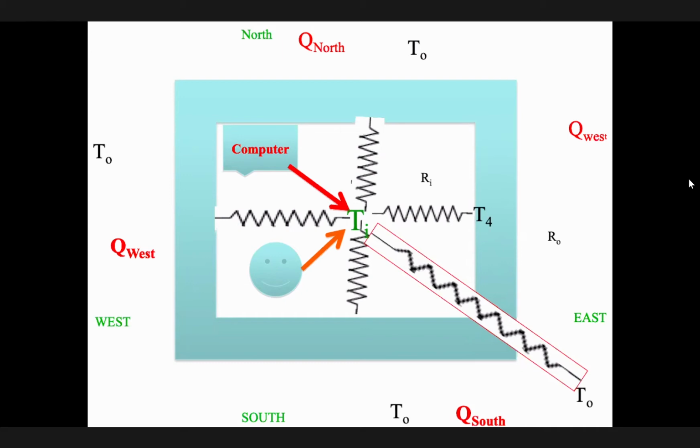Again, remember how much energy you add to the room from the occupant, how much energy from the computer you have, and you can make an assumption that this guy is making coffee, therefore there's a coffee machine over there, and that's all, okay? Therefore, make your assumptions, use your judgment and look at the number to see if it makes sense, through the wall and the room temperature and outside.